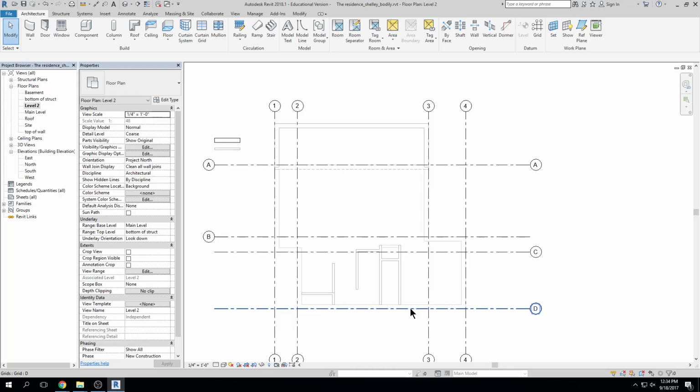And let me say this, if you don't feel like you need to link the CAD file in, don't do it. I'm just saying it's a good idea because you're still kind of new at this, figuring it out. But you might be able to use the dimensions on the CAD file from AutoCAD and the existing information you have to draw, right? So that's really helpful. Now, one thing about this is that it will print. So if you leave this on and you print, you'll get a ghosty view of the level below, right? Which you may not want.